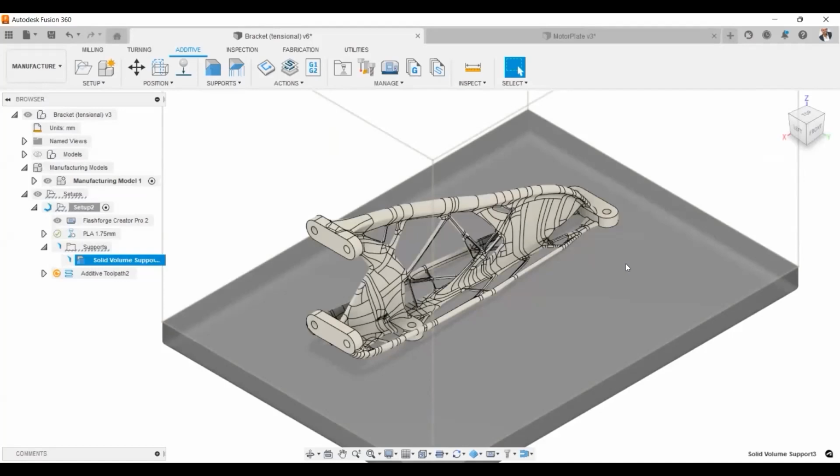So now support is very important for us, and ironing support is also quite important. But again, when you can print without support, please go ahead and print without support, because it saves you material and helps you reduce material waste. It also reduces the time, because the time it takes to print the support is also part of the time that is calculated for the final printing.